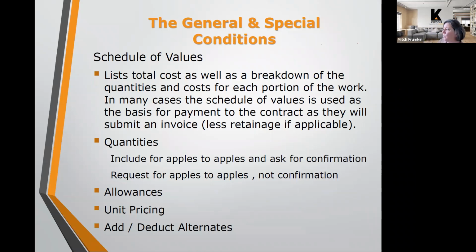Also, for example, again using a pavement project, because I do a lot of those, as you can tell, there may be changes in material costs when you're invoiced. When the contractor gives pricing for asphalt, it's based on the asphalt index, and then when you're actually invoiced for the asphalt material used in the project, that cost may increase or decrease depending upon what the asphalt index has done.